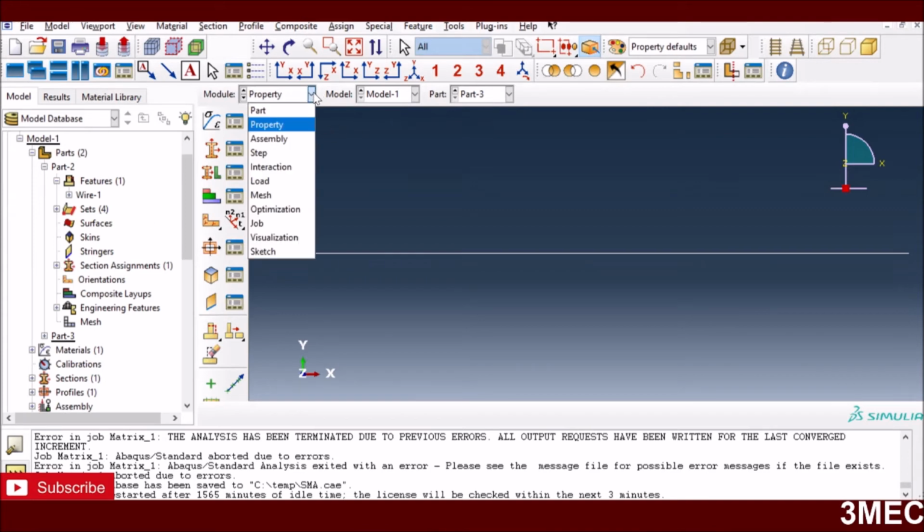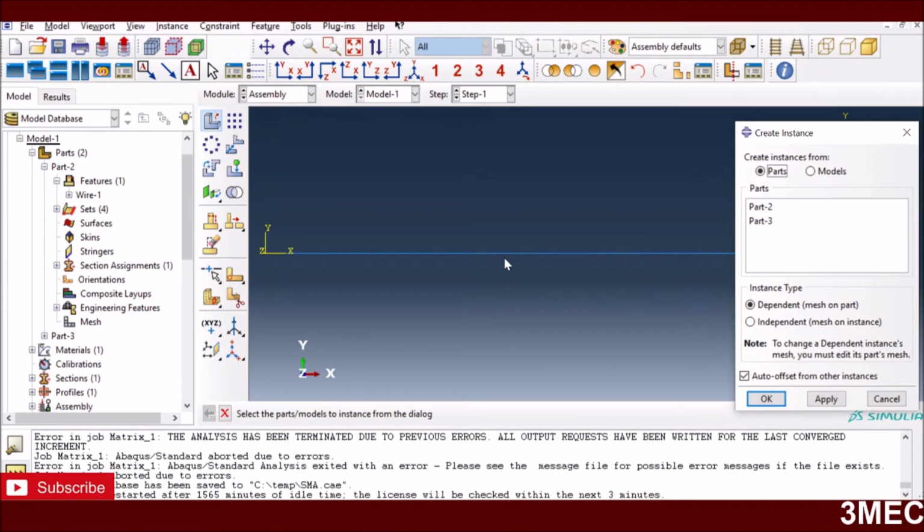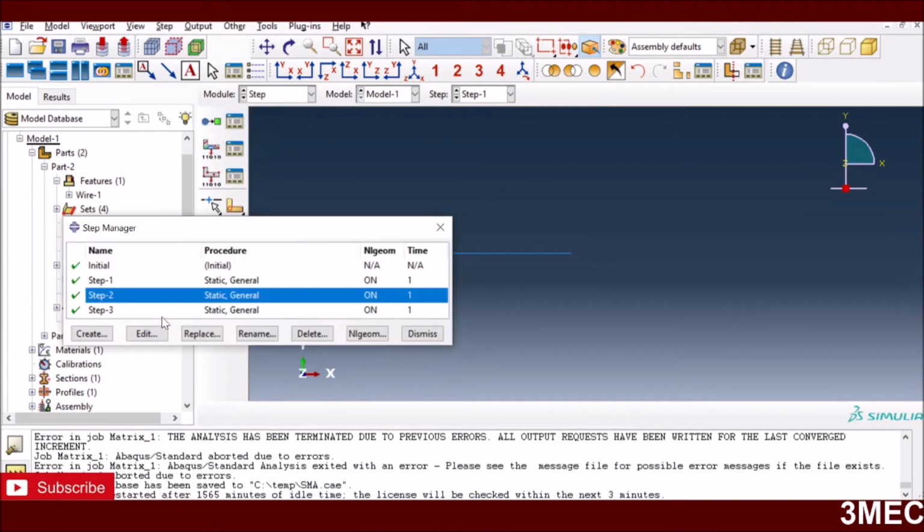And next is the assembly module. I can instance the part here, which I already have done. So this is here, just click on this and then bring it here. Okay, so that's already there. Now I go to the step and I create a general step. I have 3 steps here because in their case it was loading, then unloading, and then heating, and then again relaxing. I'm just leaving it like that for the time being, but I will explain those once we reach the next step where we have the matrix as well.